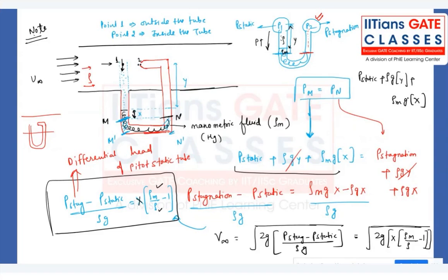And why are we applying the static law over here? Because the fluid is flowing perpendicular to the streamline inside the tube. And here why are we able to apply it for point number 2? Because point number 2 is at rest. So whatever the fluid is there, it is not flowing. It is just there inside the tube. Right? The moment the fluid starts flowing, like the GATE 2022 example I showed, we cannot apply the hydrostatic law, the static law which is for static fluid. Right? Now, once it is done, let me know, we can solve some examples.